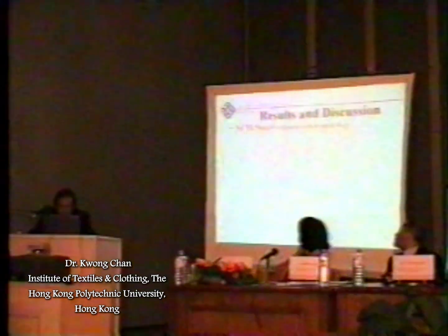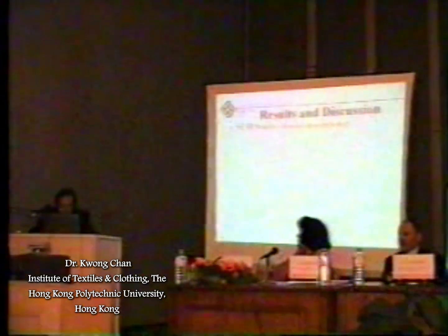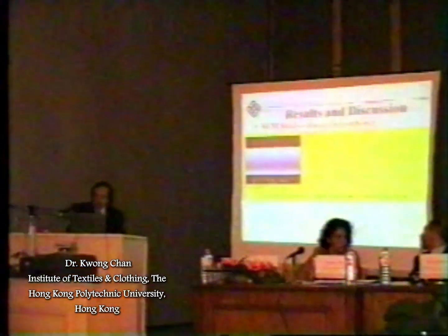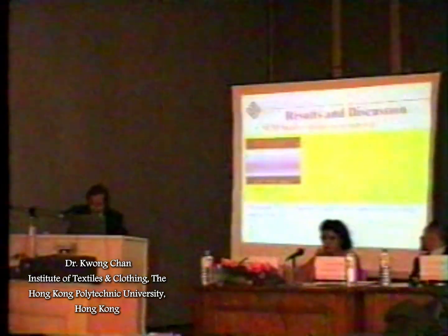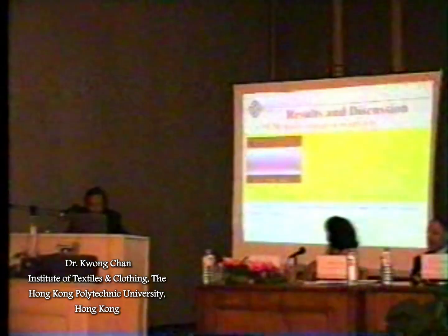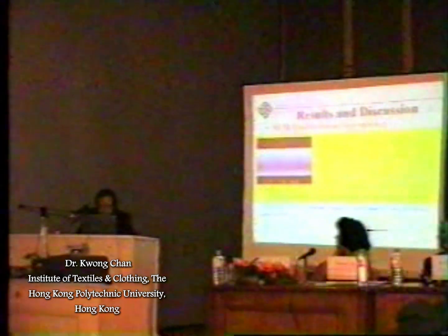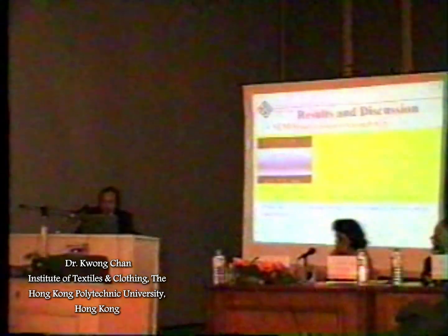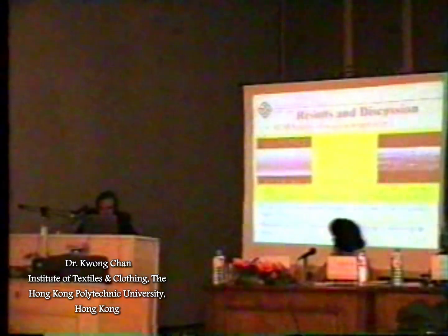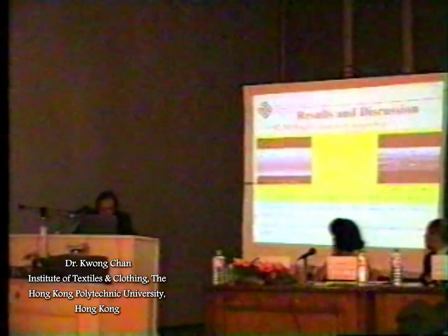So how does low fluence UV laser modify these nylon fabrics? Firstly, we will discuss the morphological changes. The scanning electron microscope helps to study the changes in morphology. In figure 1A, when the laser fluence is low, no structuring can be observed. For the high fluence, 20 mJ, melting occurs on the surface of the sample.